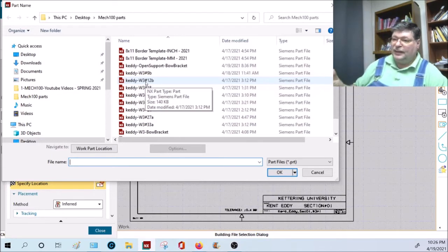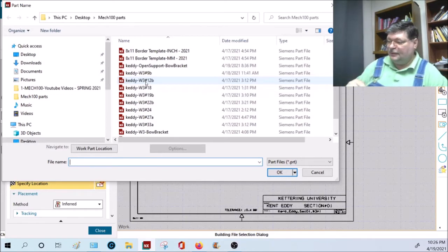And once you reference a model into your template, don't change the original name of the model, because if you change the original name of the model, it's going to look for that original name and won't find it, and it won't be able to update it again.